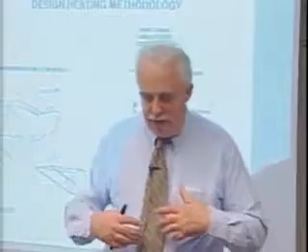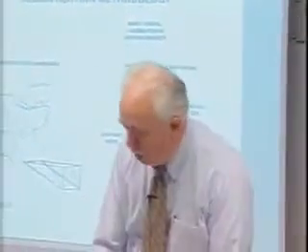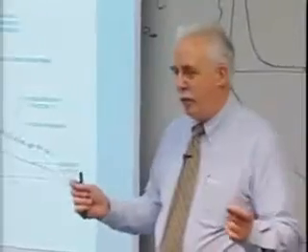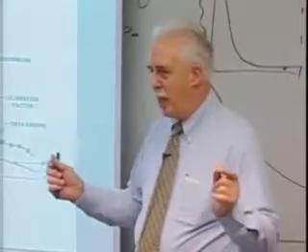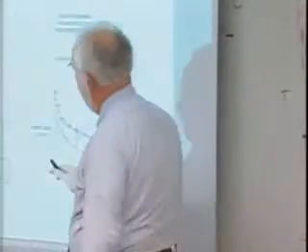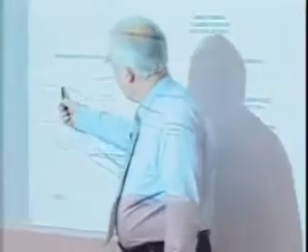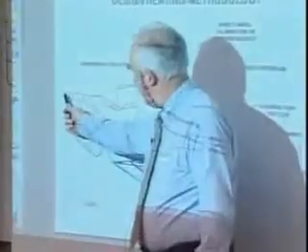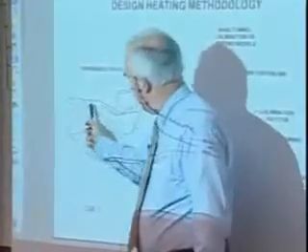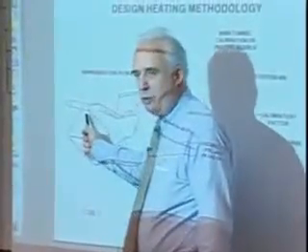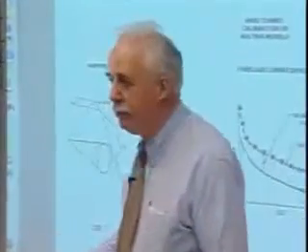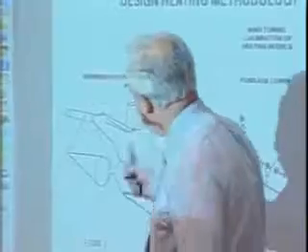Now, the way this was modeled, when we started, we didn't have computational fluid dynamics. The design methodology that was used to actually design the system was to model the flow. Obviously, up front here, it looks kind of like a sphere. And so I calculate the heating on a sphere. I go into a wind tunnel and look at the actual data and relate that and say, oh, well, that's kind of like a sphere of 2-foot radius. Okay? So that's my heating there.